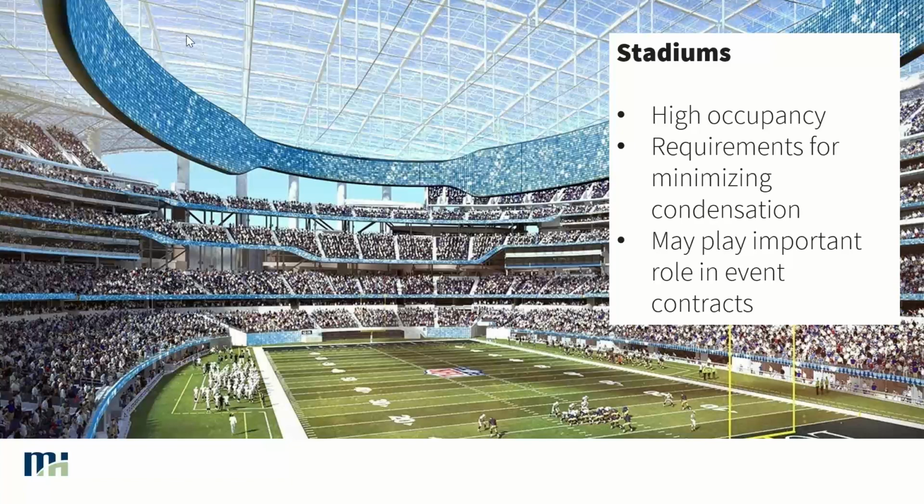So in a situation like this, you have a big enclosed roof, whether it's glazed or has some sort of polyethylene film pillowed system. If condensation starts to form on that, if it's really cold surfaces and there's a lot of people inside, then you potentially get water drips on the inside of a building when it's all enclosed.